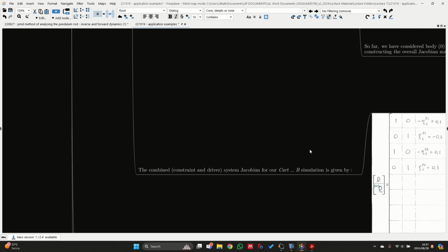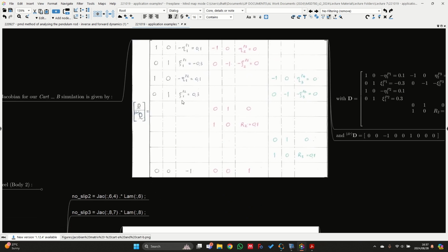Right, so if I scroll down over here, we're back to the 2 revolute joints that we first defined, and then we have the 2 disc joints which follow. They also impose 2 constraints each, so these will be the following 4 rows. Once these regular constraint Jacobians are defined, I'm going to append my driver Jacobian at the bottom as well.